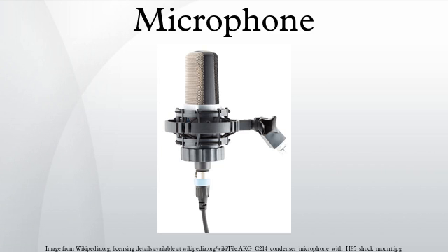Depending on the application, measurement microphones must be tested periodically and after any potentially damaging event, such as being dropped or exposed to sounds beyond the acceptable level.